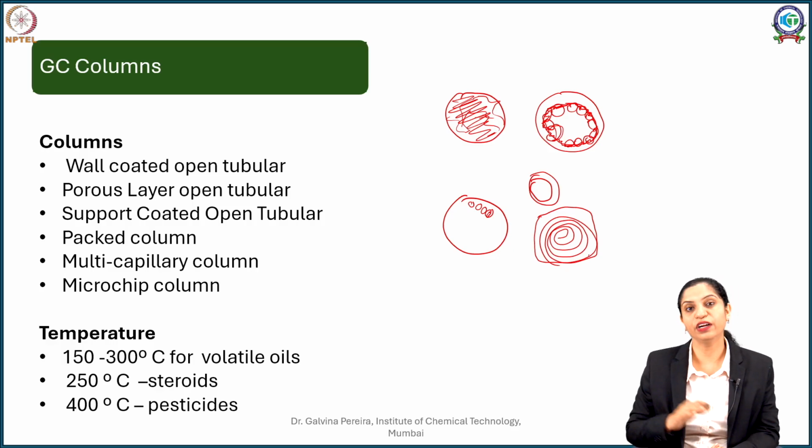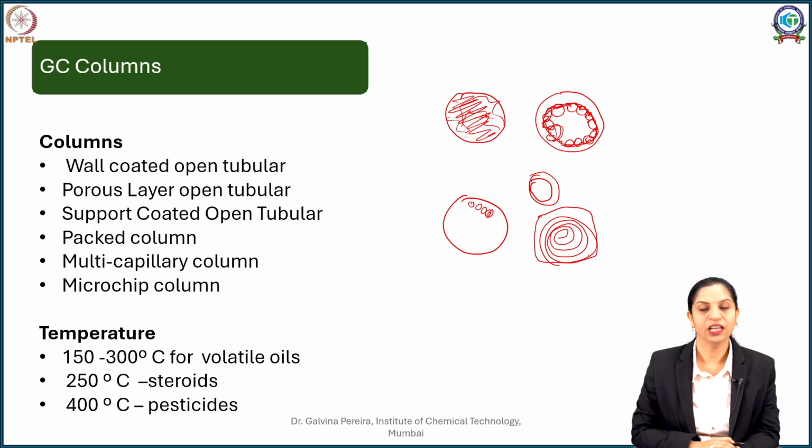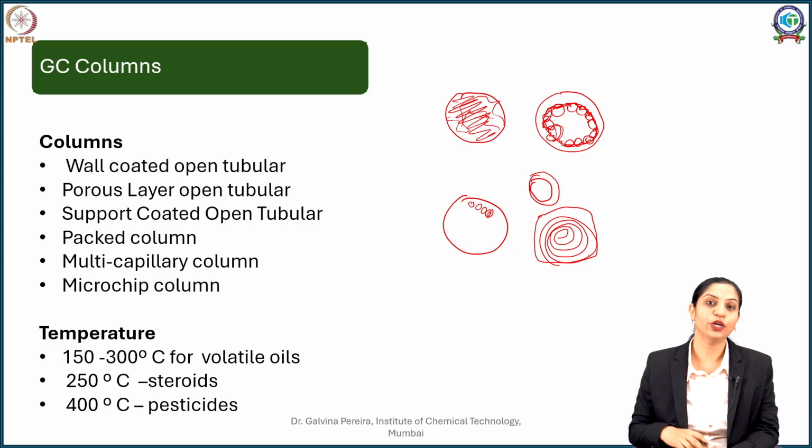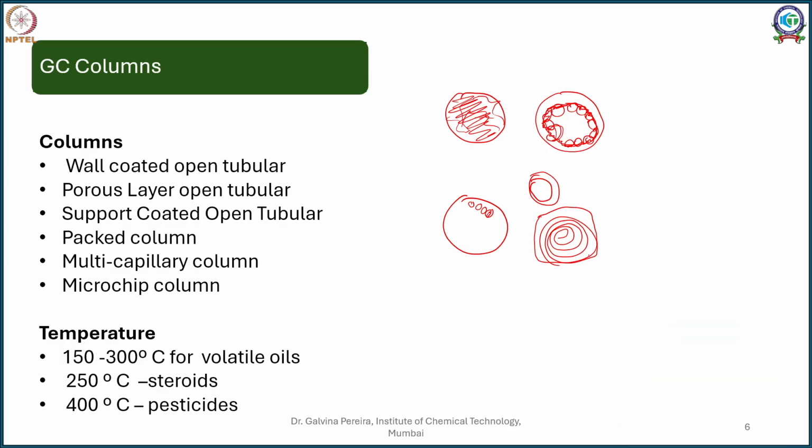Now here the different carrier gases are also important. The most efficient ones are your hydrogen and helium, but the problem with hydrogen is combustibility, so we prefer helium over it for its inertness. The other gas is nitrogen, but nitrogen slightly decreases the efficiency. Still you can use air also if you want a little cheaper substitute, and in some cases it is also blended with oxygen.